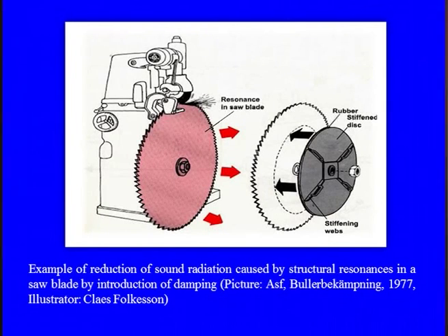You can see in the figure that we have two main parts. One is the saw blade, the circular saw, and when it is under the cutting operation, a huge amount of vibration is generated, and these fluctuations, which are at the resonant conditions, are emitted from it. Our main intention is to put this rubber feature on the blade.